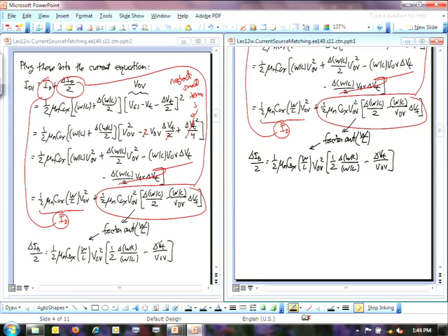So it is reduced. Okay, so that means the overvoltage that you're using to bias up your transistors, usually we like to make that overvoltage as small as possible, right? And why do we want to do that? Because it's swing, right? That determines our swing. Our V output minimum is equal to 2 overvoltages. So if you can make that overvoltage smaller, you get larger swing, larger dynamic range.